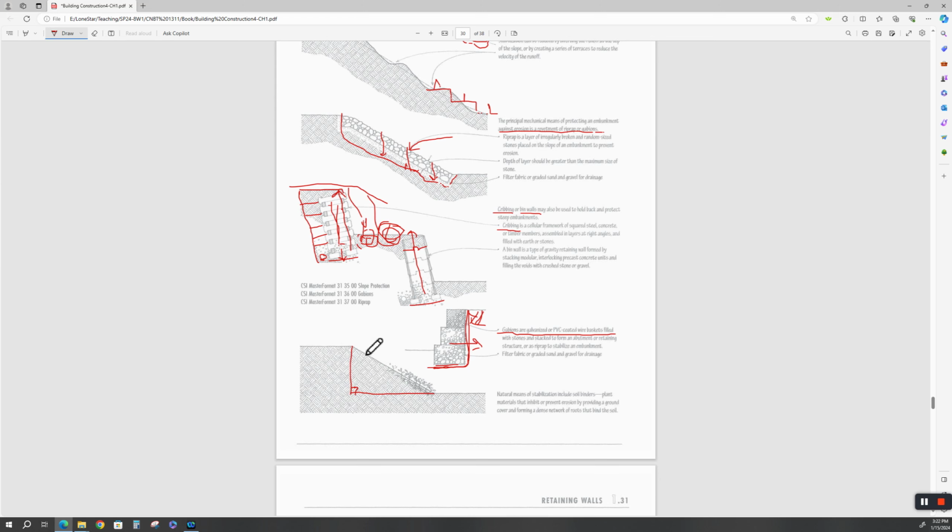So how much water is going to be shedding off of this, and what's the slope, what's the angle, how fast is that water running down, the velocity of that water? If it's too much, too fast, it'll erode your little Chinese jasmine or Japanese jasmine you planted for erosion control, right? Or if it's a tree even in here, it could erode the root structure of the tree.